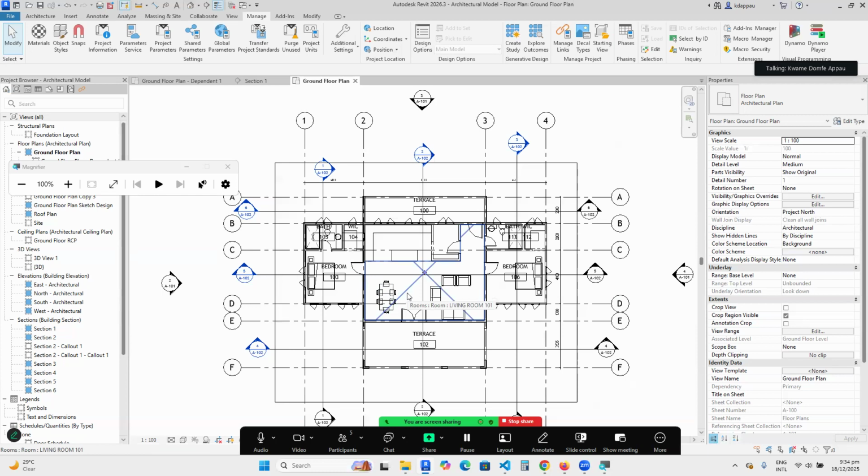That is where a template comes in. Anytime you are starting a new project, you always start with a template. That's why I've advised everybody should take one project, develop that project, do the sections, do the elevations, add the furniture, add the doors, add everything. Then later on, you see that everything will be complete. You've done your sheet, you've loaded the title blocks, you've done dimensions, you've assigned materials, you've loaded doors, furniture, and the whole project is complete. You can print it as a completed work.